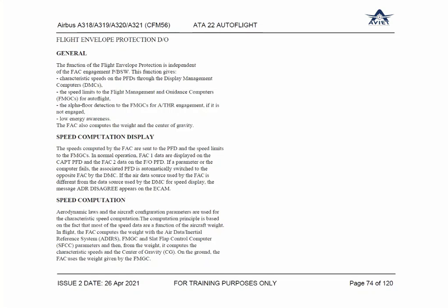In flight, when the aircraft flies, then with the help of ADIRS, in a clean configuration, the clean configuration in the cruise condition, when the parameters are stable at a given speed and Mach, then FAC will compute the actual weight of the aircraft, and that will be given to the FMGC.